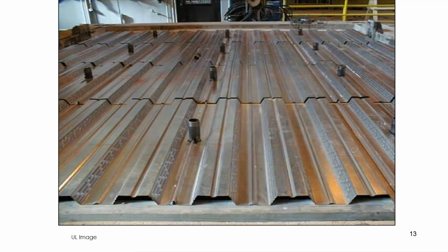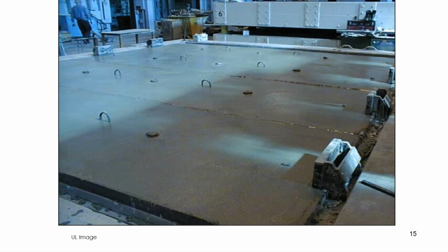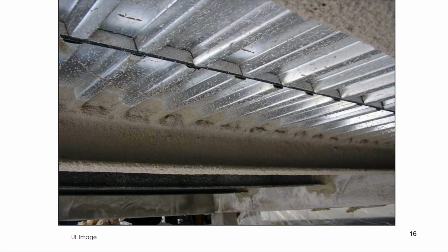The next step of the construction process would be to install the steel deck on top of those beams. And then concrete is poured on top of the beam, leveled smooth as would be done in the field. And then the assembly is allowed to condition. Concrete typically will take 4 to 6 months to condition or cure prior to the fire exposure test. Once the concrete has cured, the assembly is turned over to the sponsor of the test, who will then apply whatever protection material they're testing to the underside of that assembly. And prior to the application of that material, the testing laboratory will install thermocouples on the steel or in the steel so that they can measure the temperature during the fire exposure test.